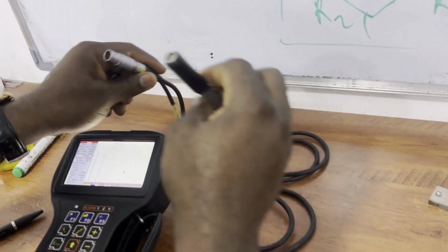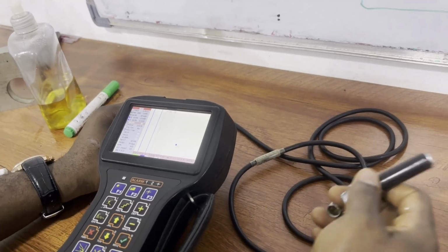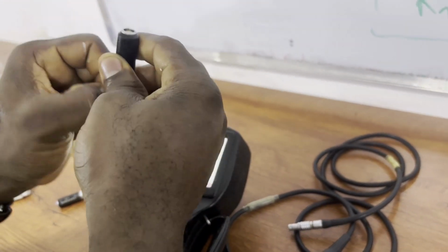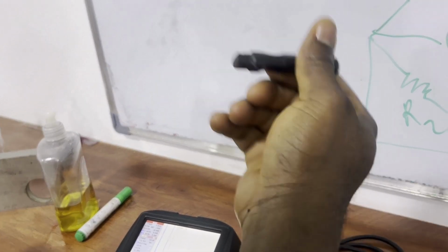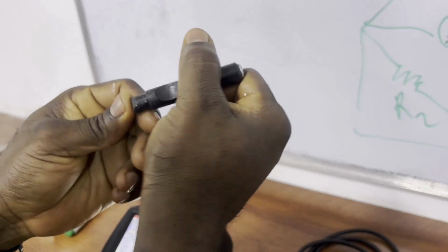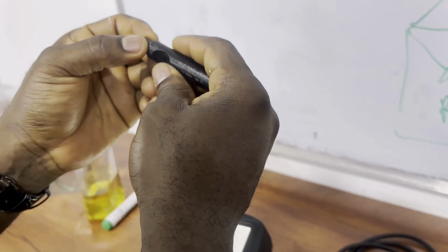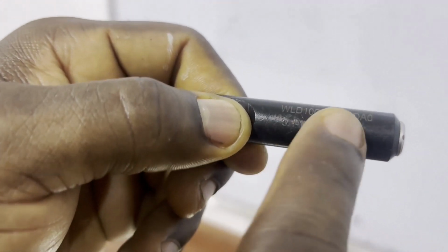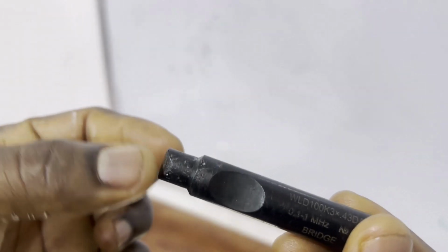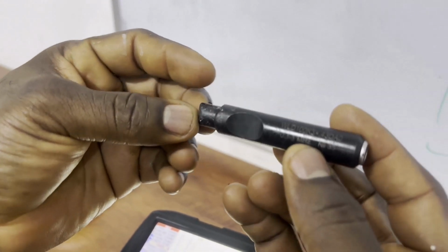We've had cases of personnel go to work and they went with a bad probe. They did not know. If I take out this duct tape, by principle, this is actually a surface probe, even though the surface is curved, and this is a bridge probe. How do you know? If you look at the body of the probe, it's clearly written. But even without being written, normally this is how a bridge probe comes. I will talk about that in some other video where we look at the types of probes for eddy current.